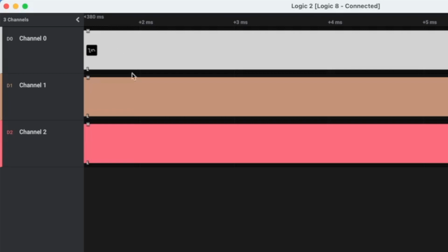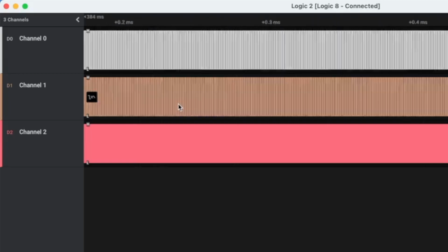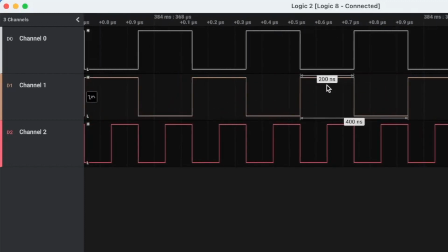pretty perfect clock cycle. Then we're looking at the not clock, the inversion of the main clock. As you can see, it's high when the other clock is low. It also has some fluctuation, and it will be mainly used for the control module and stuff like that, so we can prepare instructions on the first half of an operation. Technically not first half, but like we can prepare an operation before the main clock pulse.